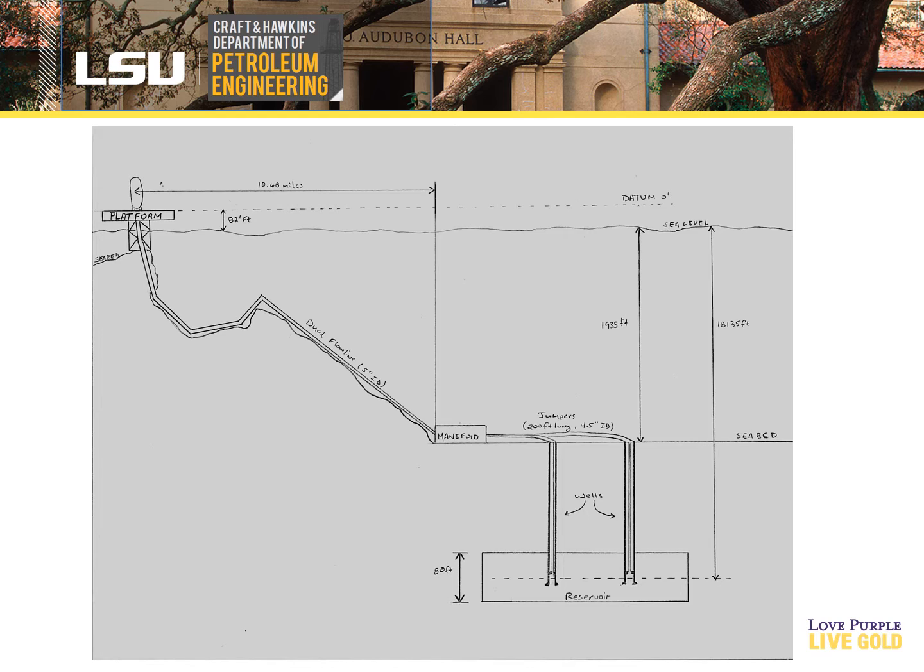This dual flow line will cover a horizontal distance of 12.68 miles along the seabed until finally reaching its destination at the platform. The platform sits at 82 feet above mean sea level and is where the dual flow line will connect with our separator. This separator operates at 500 psi and has a maximum liquid handling capacity of 10,000 stock tank barrels per day.